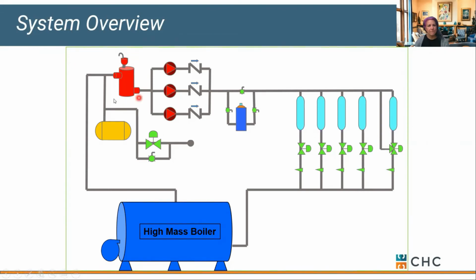And my air separator, when would I troubleshoot that? Well, if I'm having some air issues on multiple zones, kind of some sporadic heat or cooling issues, it's more heat than cooling, but if I'm having sporadic problems in my system, it might be that somebody has valved off my high-capacity air vent. We've seen guys put a plug here and put their high-capacity air vent somewhere else in the system. That doesn't work so well either, okay? But all these are minor components, but boy, they have a big effect on how the boiler operates in our system as well as the pumps.